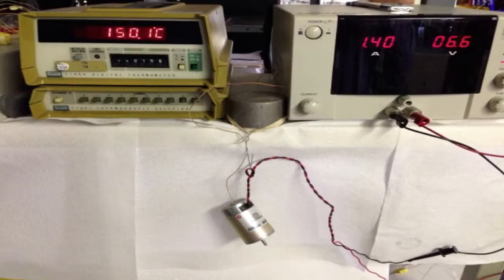Pittman motor data for the 6000, 8000, 9000, and 14000 series is based on tests where our motors are suspended by wires in standing air at room temperature, or 25°C. The rotor is locked to prevent rotation. You can see the thermal probe indicates the internal temperature of the armature. This setup minimizes the amount of heat transferred due to contact directly or through a medium.